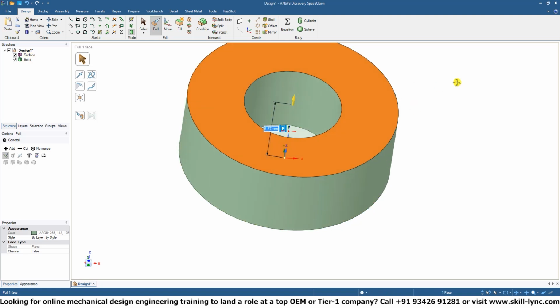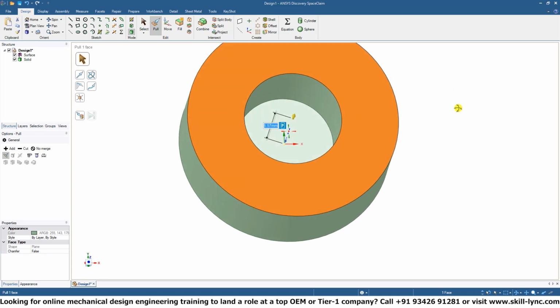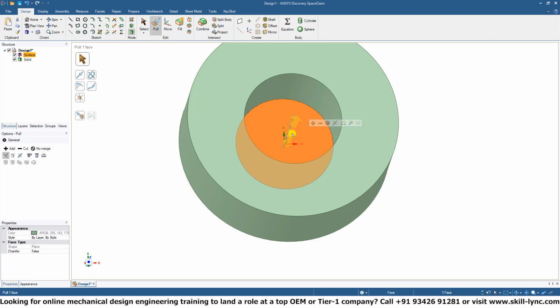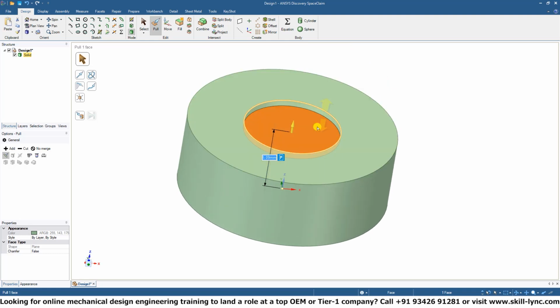It only affects the outer area of the circle. But what if we wanted to pull all of the area, encapsulated by both of the circles? You could also click the inner area and pull this out as well. But obviously, it's not that easy to actually align them through one pull operation. There is a much simpler way to do this.